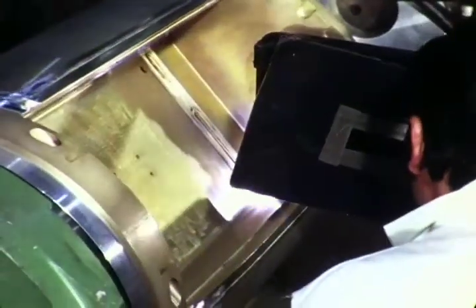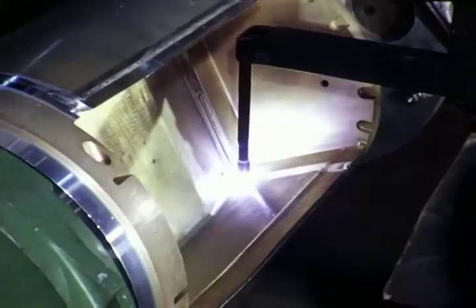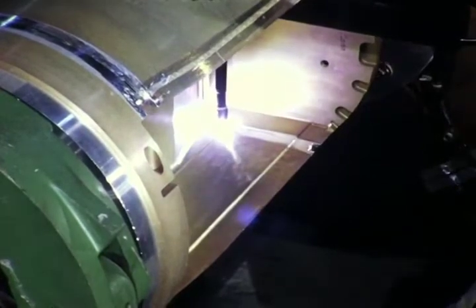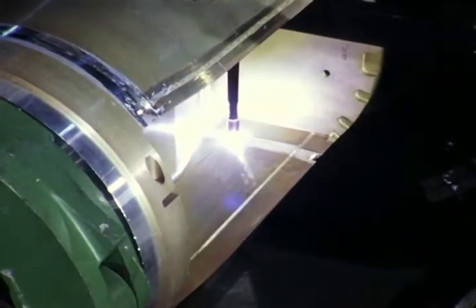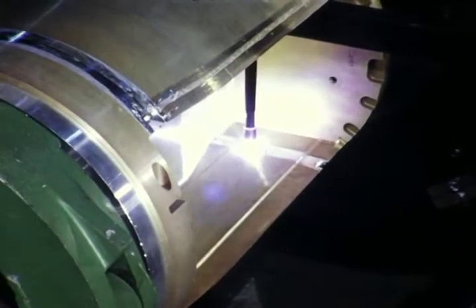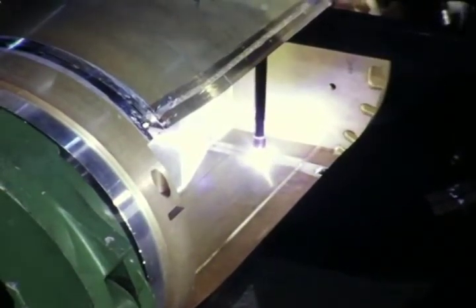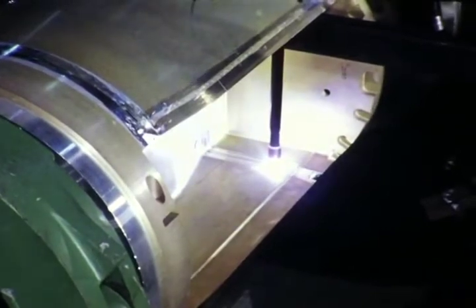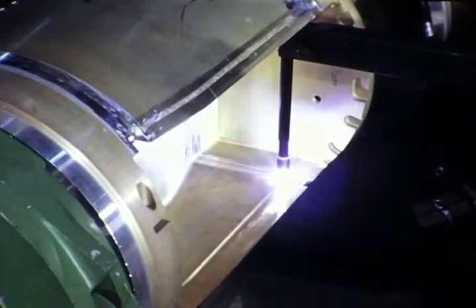Welding current and voltage, as well as the turntable speed, are programmed continually throughout these corners. An inherent part of the application program is to maintain the surface of the part level below the torch. This provides stability of the weld puddle, resulting in good bead contour, even in the most severe corner of short radius.